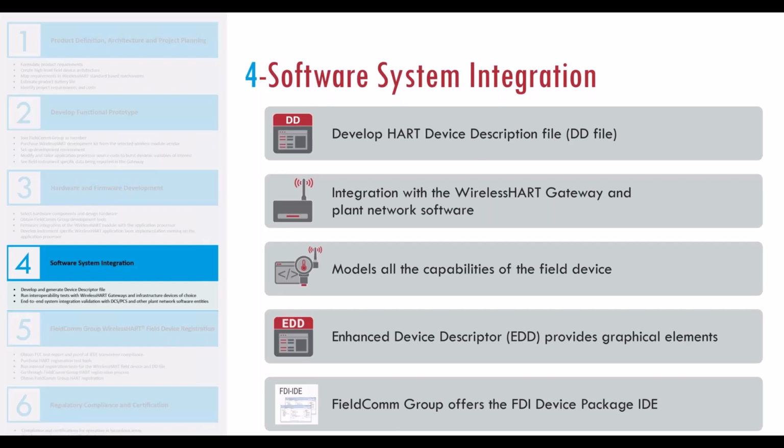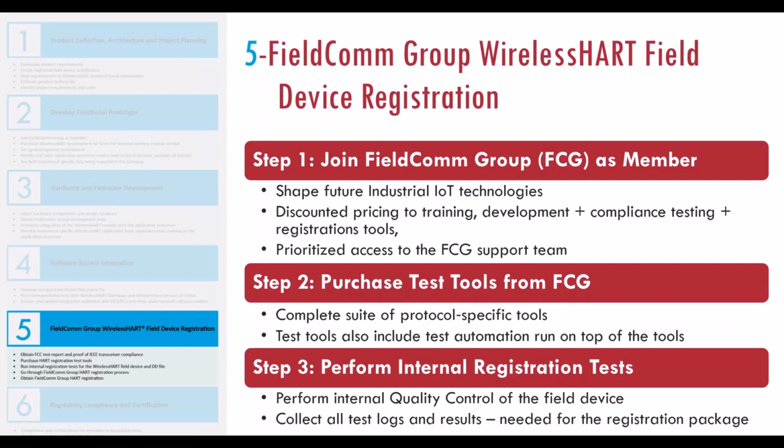Now, you can also develop an EDD, an enhanced device descriptor file. And FieldComm does offer the FDI device package ID, which will allow you to develop this file. Or you can come to us at Centero and we'll help you develop this file. Let's move right along. At this point, if you have developed your instrument, validated your instrument, and written the DD file, you are most likely ready to submit the instrument for FieldComm Group device registration.